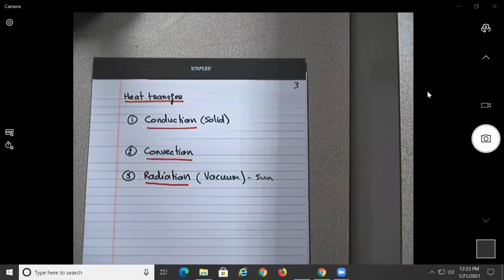Now, how fast the heat is going to go from the outside to the inside depends on the insulation properties of your wall, no? So for example, if you have the first layer, let's say, to go to extremes, is metal. Does the heat transfer quickly through metal? Yes, so that would not be a good solution. Your house will get hot very quickly. Now, let's say after the metal you have an insulation, whatever, let's say you have wood dust. Does the heat transfer well through wood? No, so it's some kind of insulation, no?